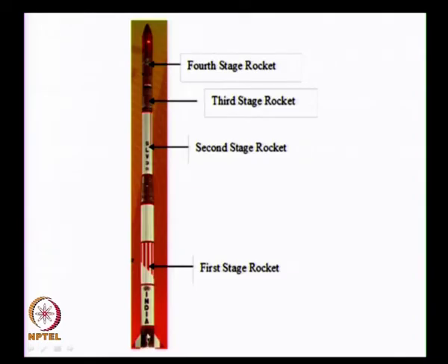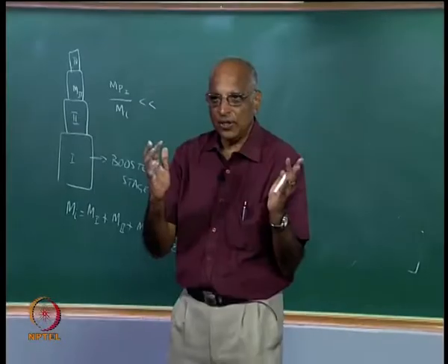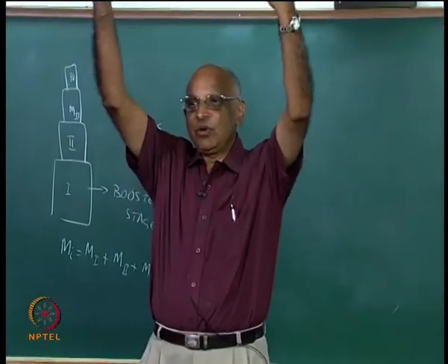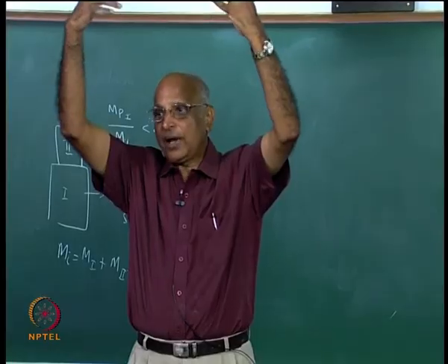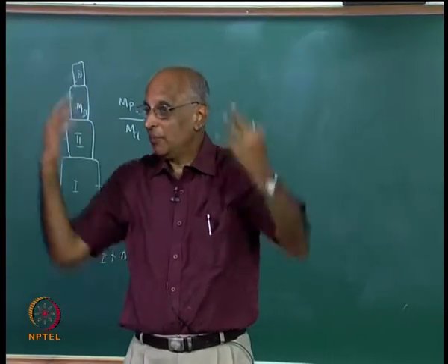The total velocity which the rocket gives is delta V1 for the first one, delta V2 for the second one, delta V3 for the third one, delta V4 for this one, and maybe we will work out this problem a little later. All I want to say is, well, we had a 4-stage vehicle. It is very deceptive; sometimes we feel we can keep on increasing the number of stages, maybe make infinity stages. I can go on and put any velocity I want, but it is not correct.